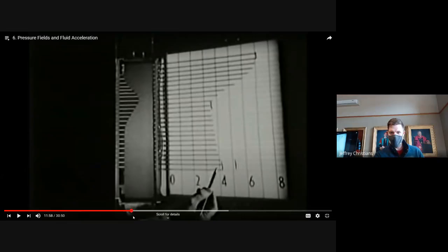But hopefully, these are the two pictures for C that you should have. So obviously for this one, for the faster expansion, we're seeing visually that we went from getting up to a pressure here of 5 and a little bit, to now 4 and a little bit. So we have a pretty significantly larger amount of head loss when we have this faster expansion.